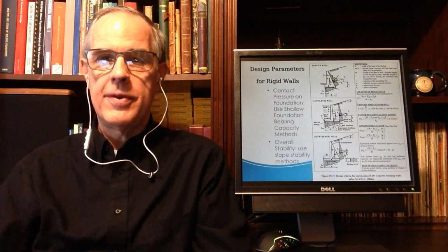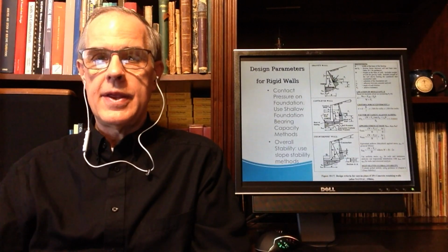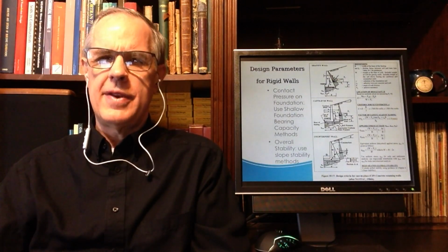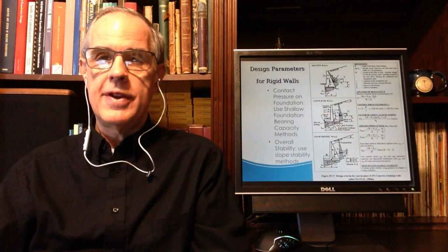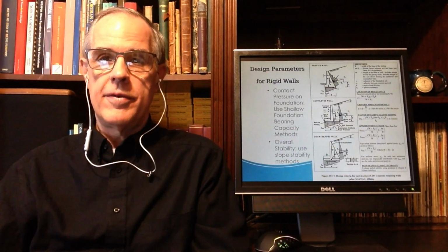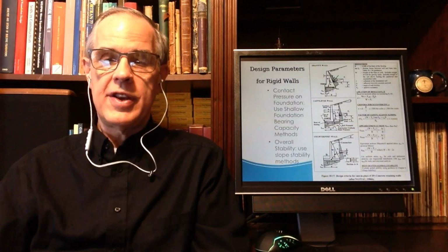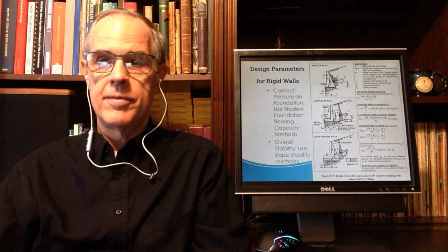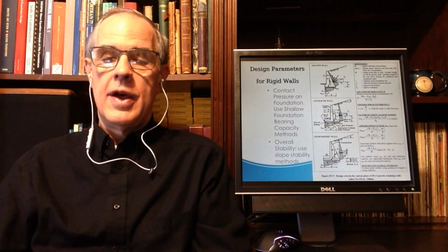It helps keep the wall from overturning, and in an indirect sense from sliding as well. In other words, that piece of soil becomes part of the wall itself, and we're leveraging the weight of the soil in that endeavor, so that we reduce the amount of concrete required.